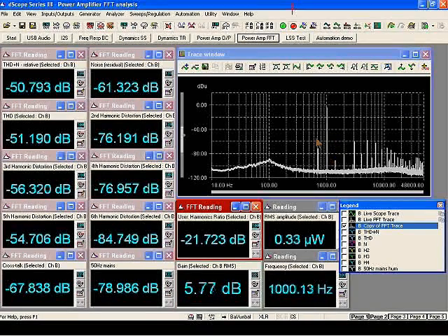device is actually performing. So these spectral processing tools, these smart FFTs, are a really powerful way of measuring all of these types of parameters all at the same time and allowing us to track trade-offs between different parameters as we refine our design, or simply allowing us to quantify all of these results in a very short space of time if we're interested in verification testing or potentially production line testing applications.